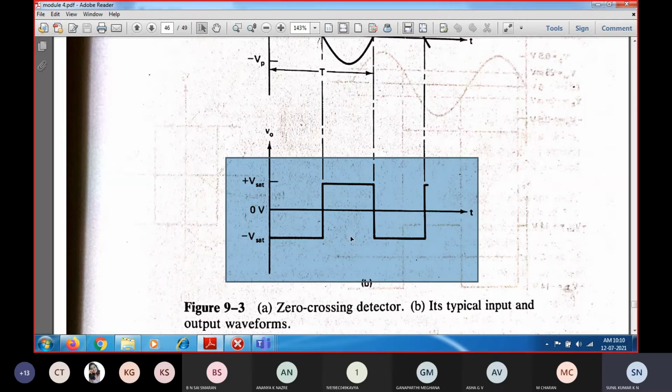That will be provided by the crystal oscillator. Because of that, as I just told, in all digital applications and digital circuits, we are going to obtain the clock frequency based upon the crystal oscillator frequency, which will be treated as the clock frequency. Even in microcontrollers, you might have studied, 11.0592 megahertz will be the frequency of the microcontroller. That is the oscillation frequency, the oscillator frequency. That is also going to be generated from the crystal.